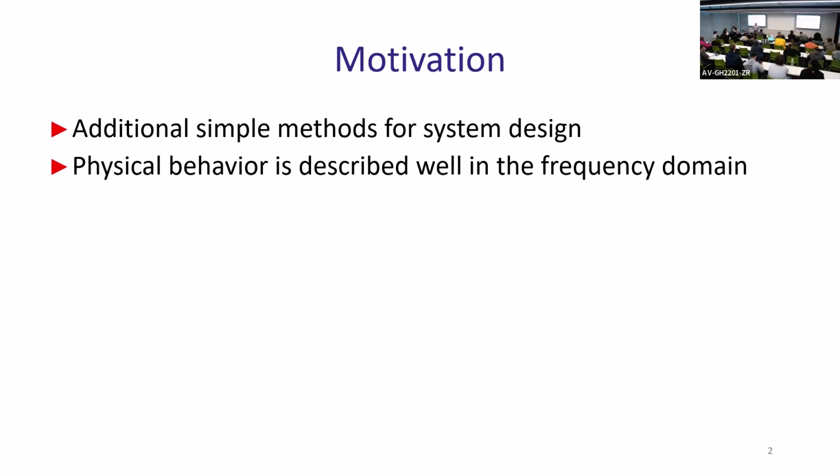You cannot directly connect the location of poles and zeros to important things like settling time, overshoot. You have only approximations of some kind. And in the frequency domain, it's much more physical. So you have some physical meaning behind Bode diagrams. It's the actual gain response to particular frequencies. And these frequencies appear in actual physical systems. So it's important to understand what you do with that type of gain systems.